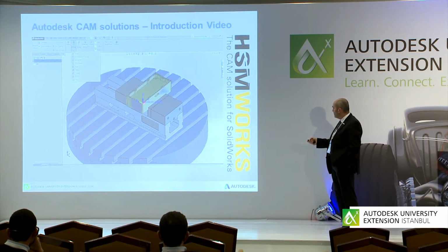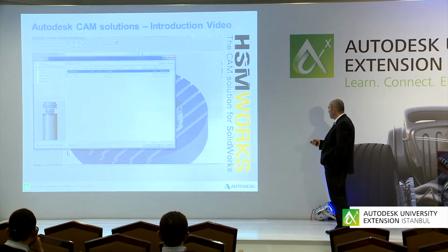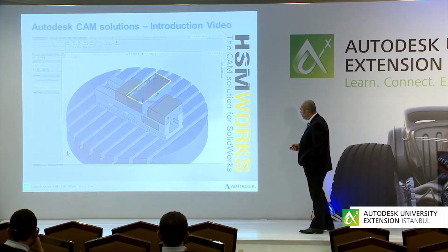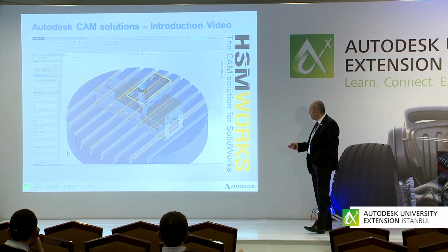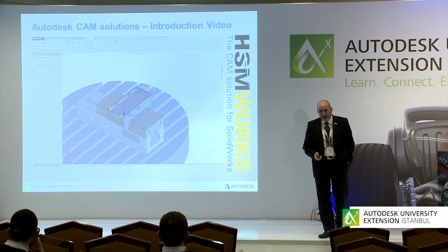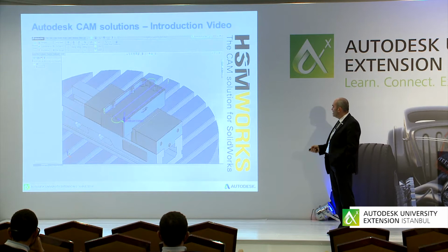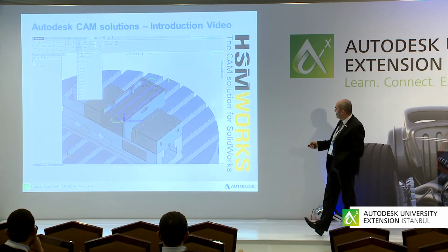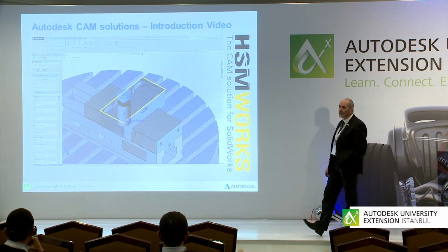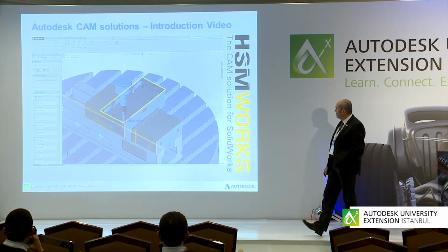One thing that is really urgent to know: the machine setting, or the coordinate system orientation, must not be the CAD orientation. If you use a non-integrated CAM system, sometimes it's not easy to set the right direction. Again, this coordinate system reflects the machine setting in your machine shop. You select the tool. With the tool come feeds and speeds automatically.